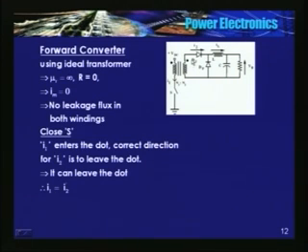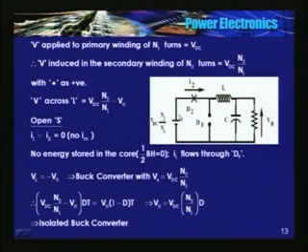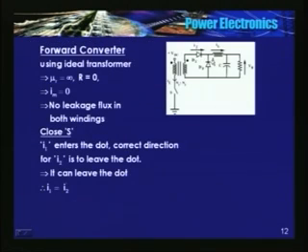So in the equivalent circuit you see here, the diode is conducting, inductor, output stage back here. DF is off. See in this circuit, diode DF is off because this is positive, this is also positive, this is negative, a reverse voltage appeared across the diode. So diode DF is off.